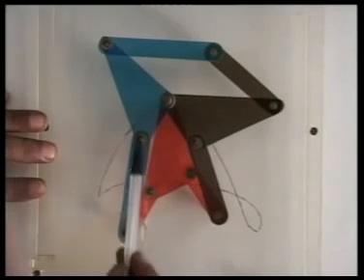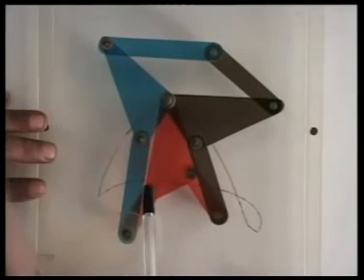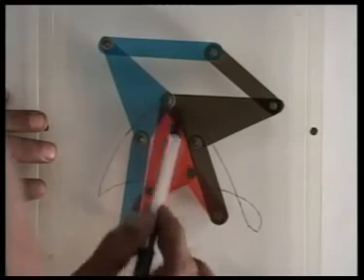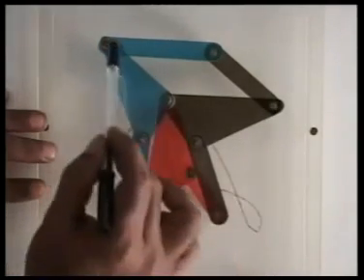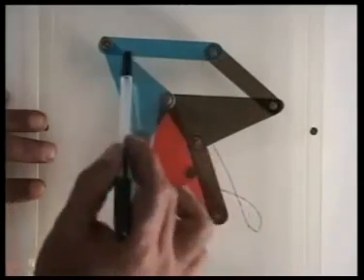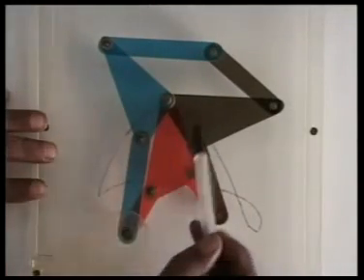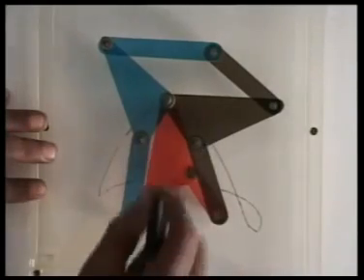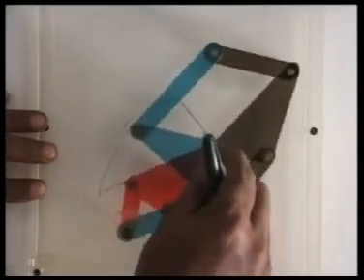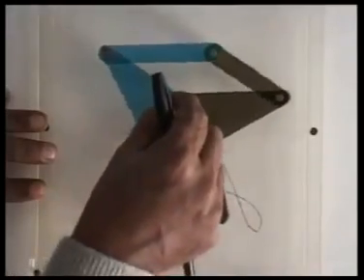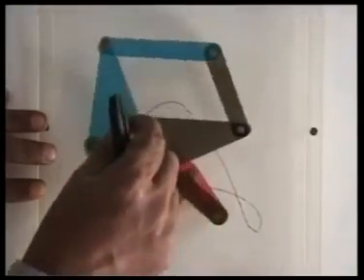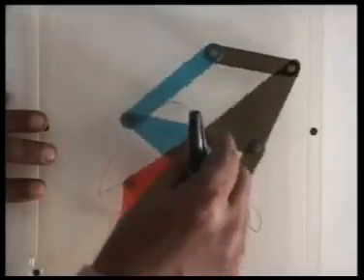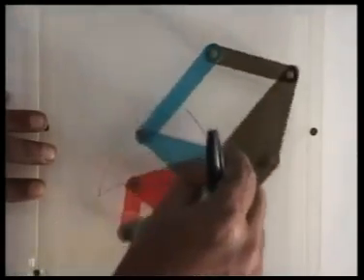But notice that these 4 hinges constitute a parallelogram, so do these 4, and these 4 hinges also constitute another parallelogram. And these 3 triangles, the ternary links, are similar to each other. Consequently, this constitutes a single degree of freedom mechanism which is an overclosed linkage which has mobility. It is not a structure.